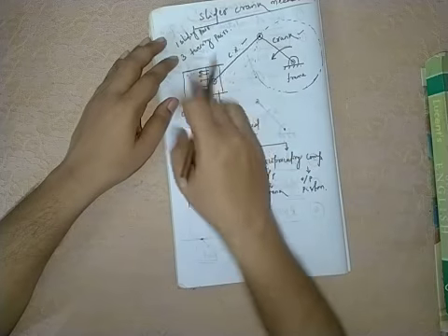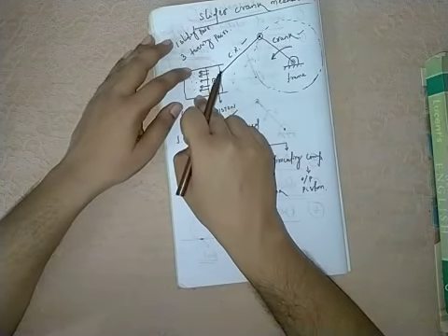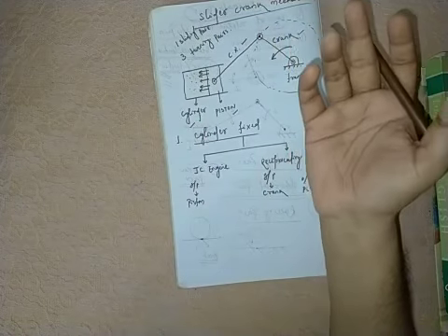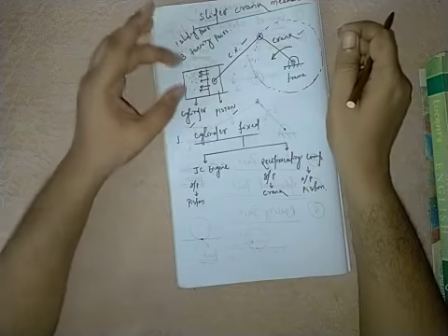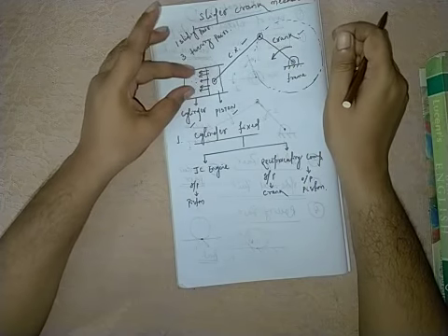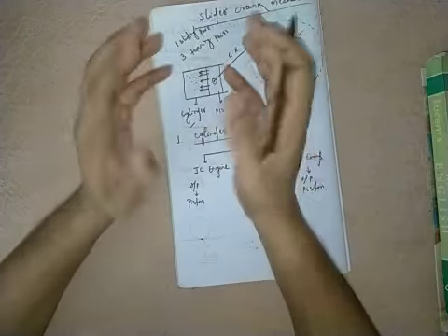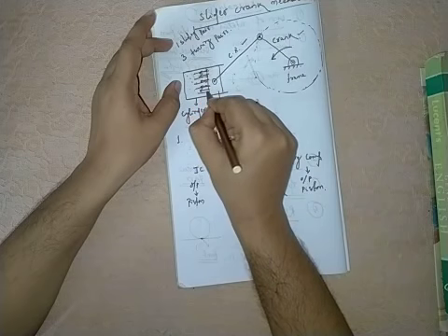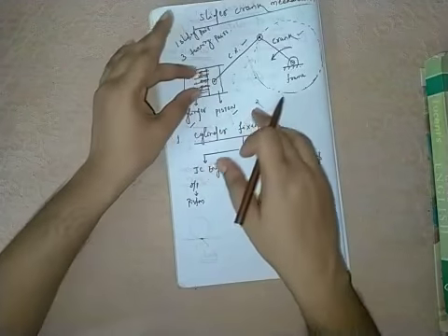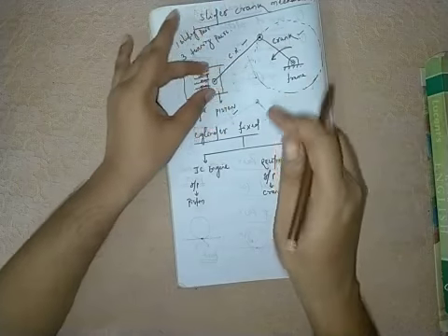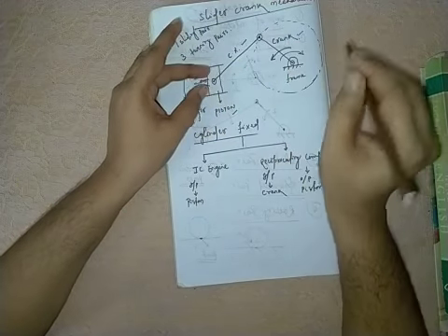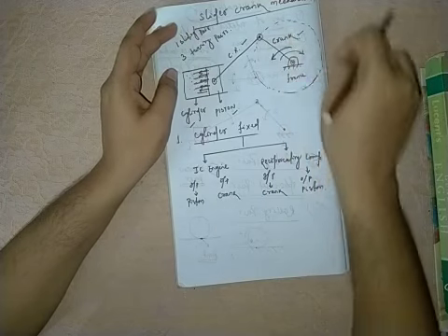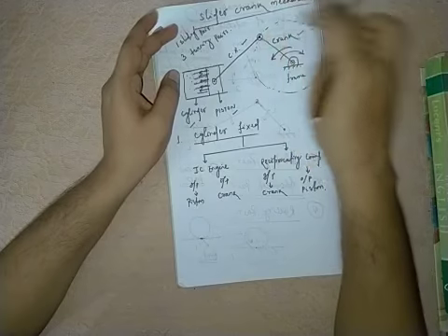means if you are burning the fuel inside the engine cylinder, as you already studied this part in your third semester, I think. So as you are burning the fuel inside the cylinder, the gas produced by the burning of the fuel will force the piston in this direction. Here input is on the piston side, the piston will go in this direction to the right-hand side, and ultimately your output will be generated at the crank side, means your crank will be in rotating motion.